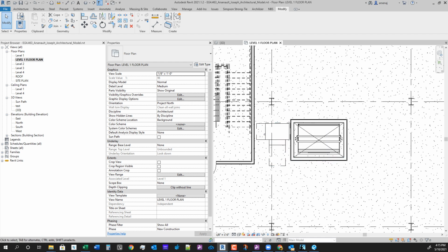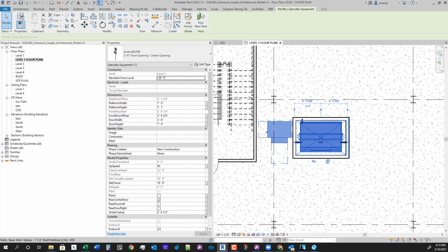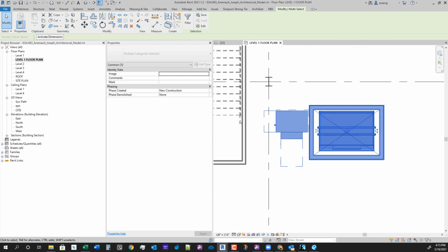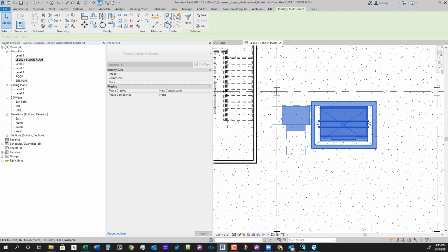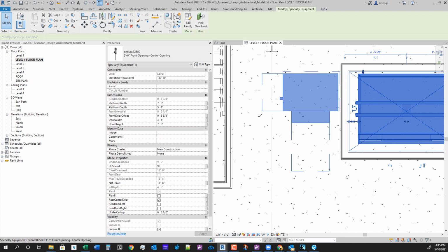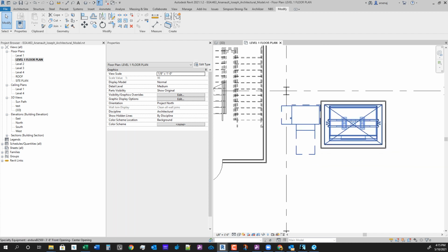So the next thing we're going to want to do is select the wall and the elevator. I'm just going to move it over slightly so that I can create this elevator room. And I'm actually going to move it down a little bit as well. To move it down, I can just grab and hold it. What I'm trying to fix here are these dashed lines, the elevator room clearances. This is what they need to be in here to operate the elevator equipment if need be.